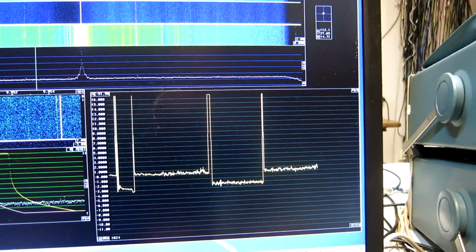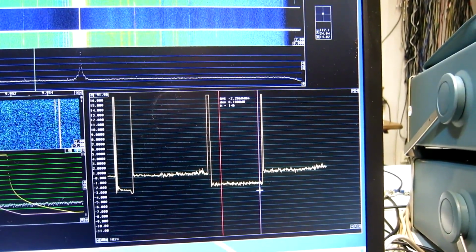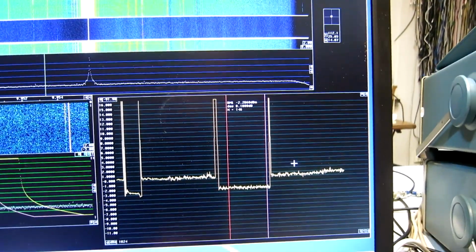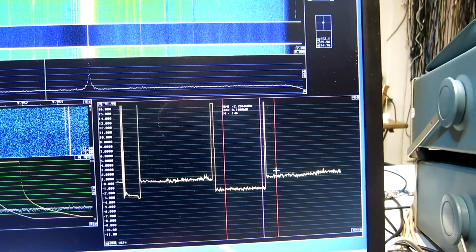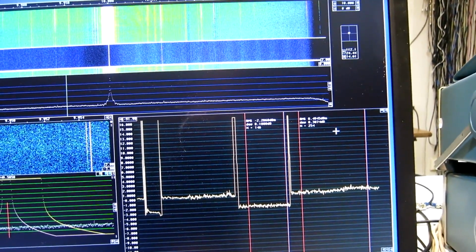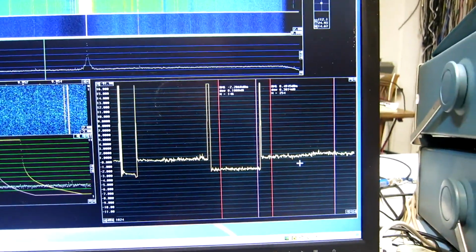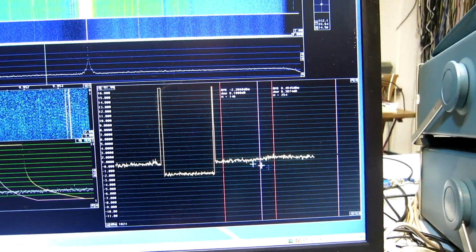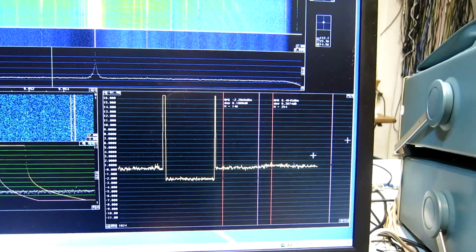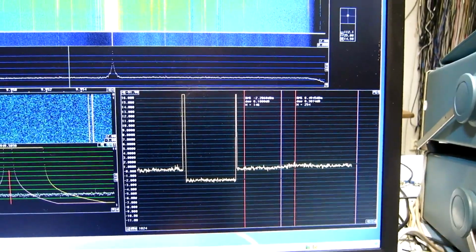So here is the difference with a large attenuator setting. Here the level is minus 2.2, and when the oscillator is running I have plus 0.5. That is a 2.7 dB difference, but I can clearly see there is a stability problem in the oscillator. But to start with, I want to know approximately what level this corresponds to.